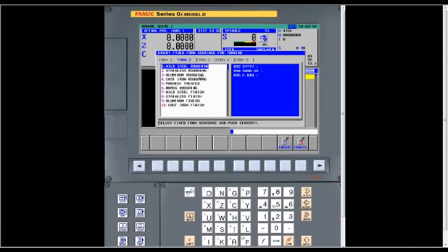And what I do in Form 2, usually I set up cut speeds for different types of material. As you can see, I've got mild steel, I've got stainless steel, aluminum, cast iron, preheat treated, brass roughing, and then finished feed rates and cut speeds for that also. And number 3, I've got drill cycles, tapping cycles, turning cycles, threading cycles, where if I don't want to use the cycles within Manual Guide I, I can just go use these, just paste them in.